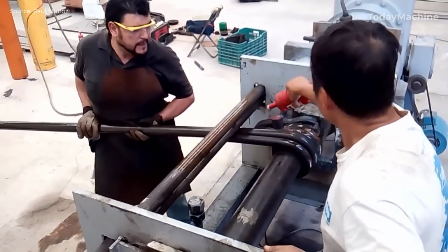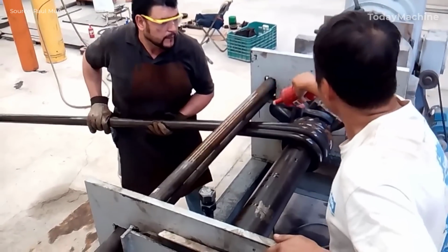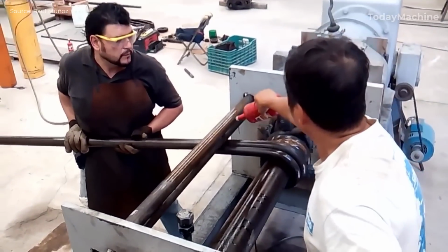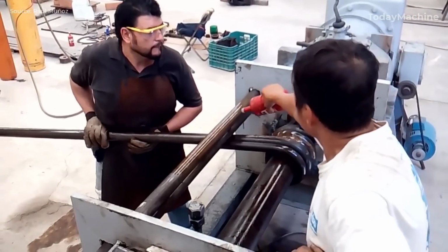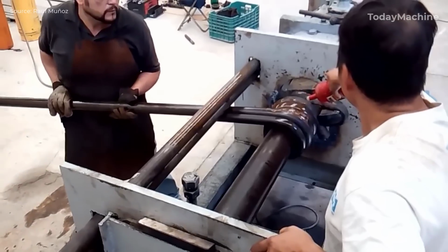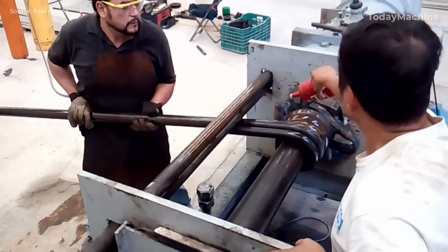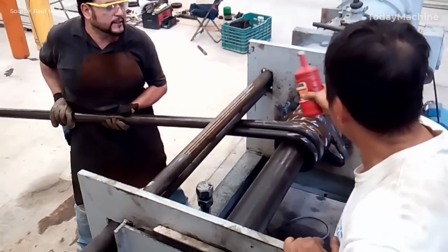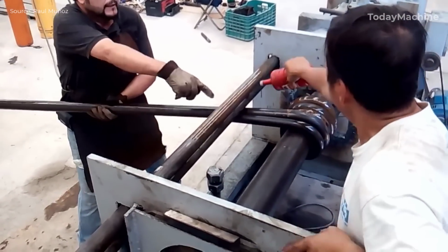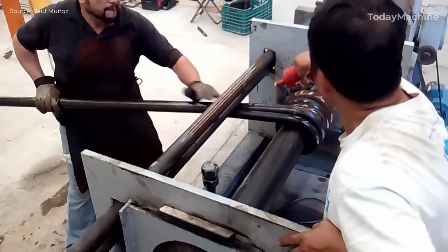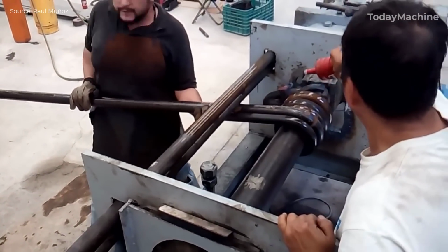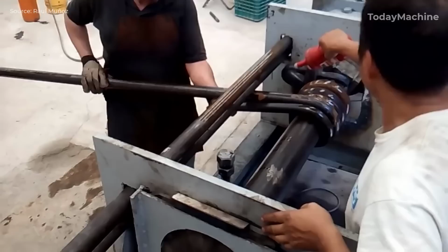Winding process. The cold winding process involves shaping the spring wire around a mandrel without preheating the material. This is achieved using a CNC, computer numerical control, coiling machine that precisely controls the tension and pitch during winding. For a 2 inches bar spring, the following parameters are typical. Mandrel diameter, 1.8 to 1.9, slightly smaller than the final spring inner diameter.